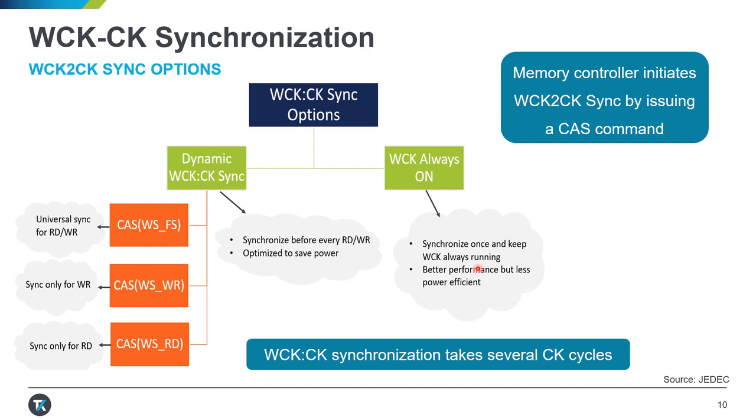But since WCK is always on, needless to say, this mode eats up a lot of power. So to summarize, a memory controller needs to make a performance versus power trade-off in selecting WCK to CK sync options.